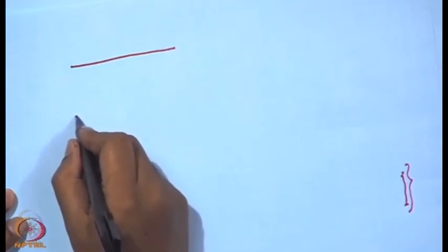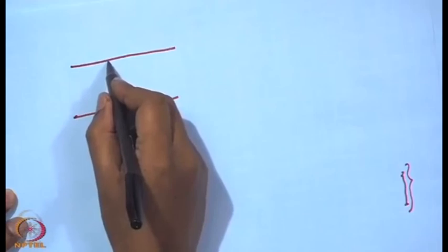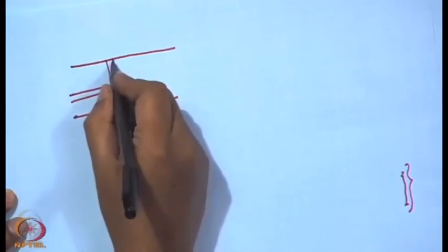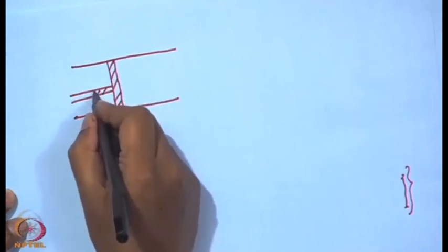and the expansion wave flattens as soon as the wave starts propagating. So, at some time after t1, the particle velocity will have a linear distribution, and similarly the pressure will also have a corresponding distribution. Let us say that we have a duct in which there is a piston.